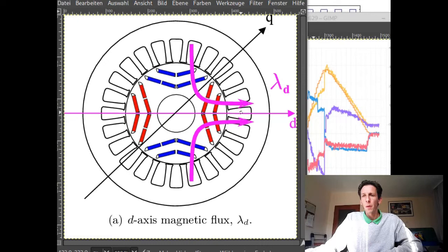And in addition, for interior permanent magnet motors, if the magnetic field is in between those two, we will be generating what's called reluctance torque. That's basically generated because the missing iron is trying to line up with the stator magnetic field. So we have 2 torque components. And that's important to know because more traditional synchronous motors with magnets stuck to the outside of the rotor only have magnetic torque, so this D component is always 0. In our case, it's not.